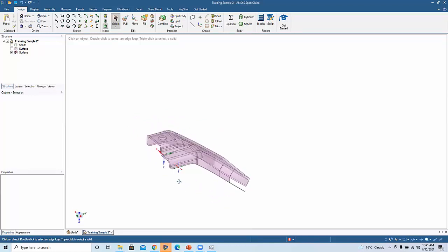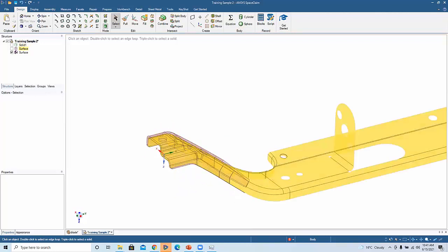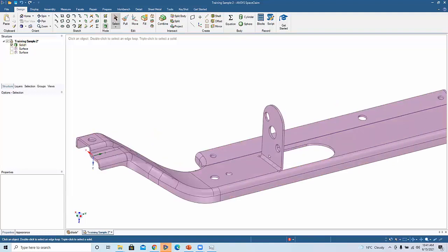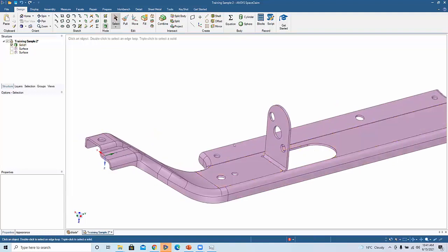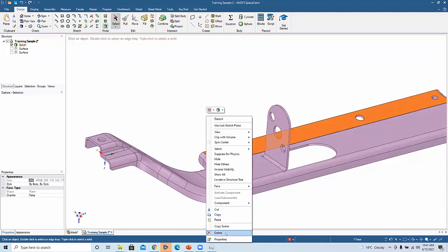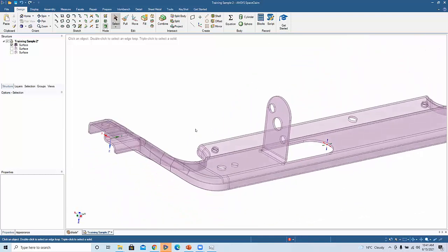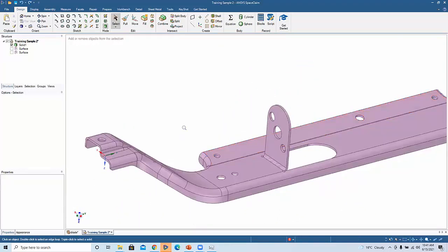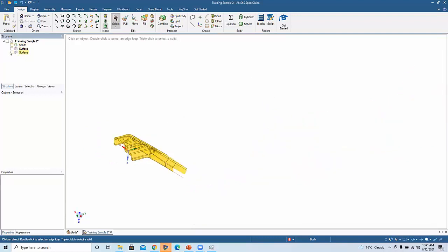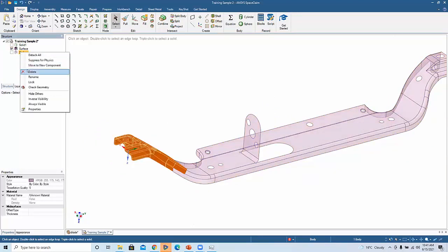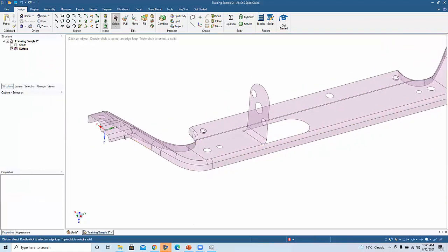And don't be intimidated when you're doing modeling with SpaceClaim when it comes to surfacing, because really at the end of the day, this model is not a solid. It's really just a bunch of surfaces that are stitched together. So if I delete that face, it's really just a surface set that's watertight. That's all these models really are. So when you're dealing with surfaces in SpaceClaim, it operates very similarly to how the pull tool works in a solid, as opposed to doing a surface.